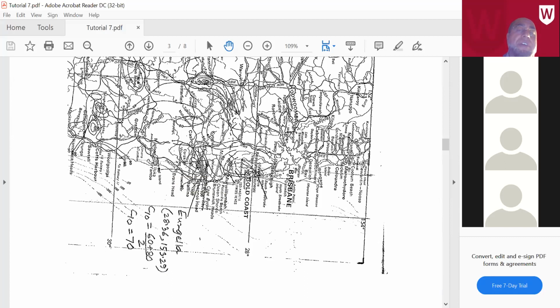60. Yeah. And then we have another contour line here, which is 80. So I am assuming that my catchment is in the middle of these two contours, which is my assumption, and then you take the average because it's in between the middle. If it is one-third distance, then you have to interpolate accordingly, so it will be closer to 80.